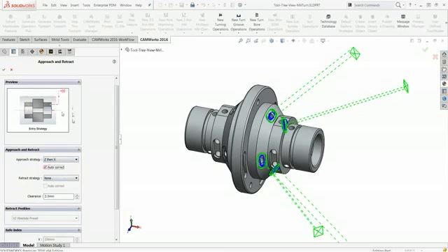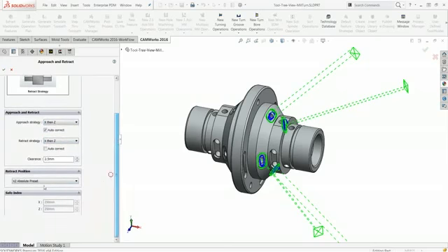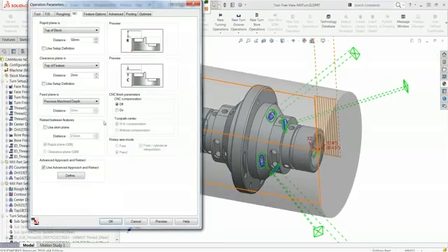I can turn that autocorrect on and it'll actually use a clearance. I can change it to none, or X and then Z. Same with the other one. So tons of different options in here. And then you've also got the retract position. You can set it to the XE absolute preset, which is the point that the actual toolpath will start at, or your program will start at. Or you can change it to a safe index and actually set up a new position. So a couple different options inside that window. And again, that's for your mill turn toolpaths under the NC tab. And you just have to turn on that use advanced approach and retract.